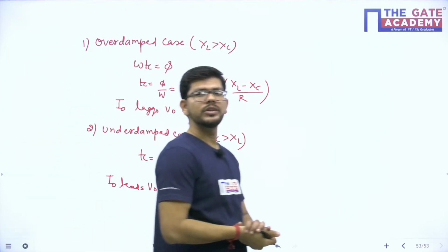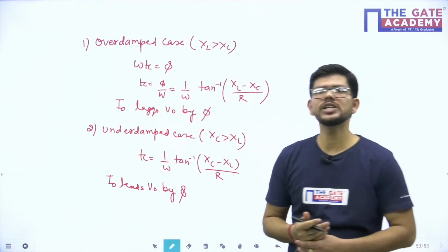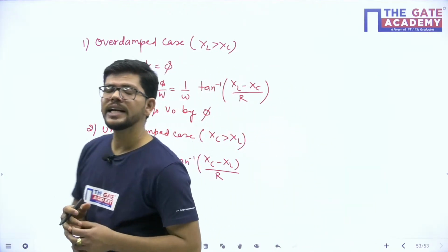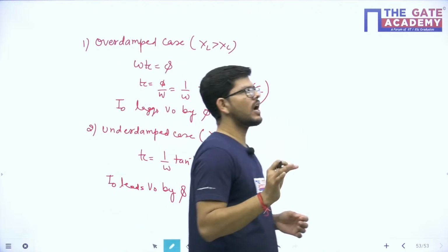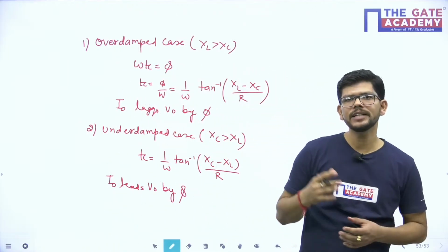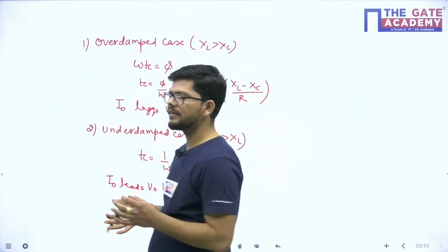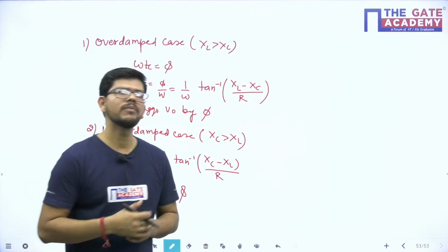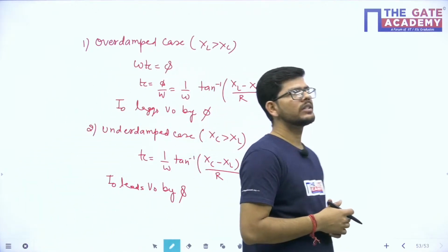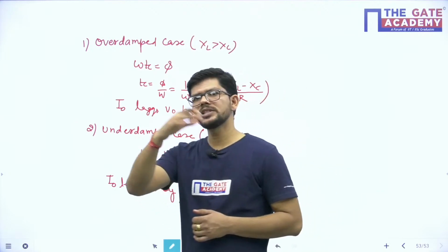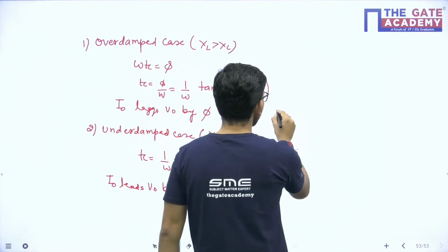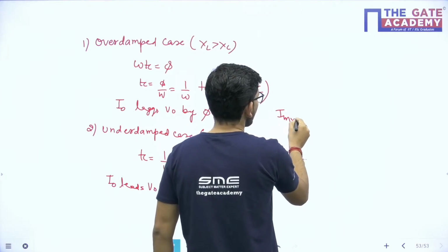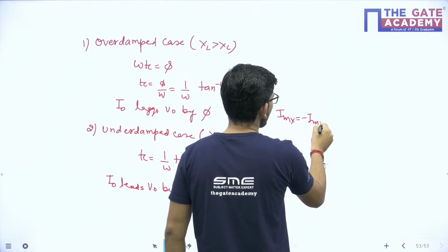So this is how we will see the variation of current in case of half bridge and full bridge inverter for different cases. For R load, voltage waveform and current waveform will have the same shape. For RL load, the current waveform will have exponentially increasing and exponentially decreasing nature. Now, what is the maximum and minimum value of current, I max and I min, in case of RL load?